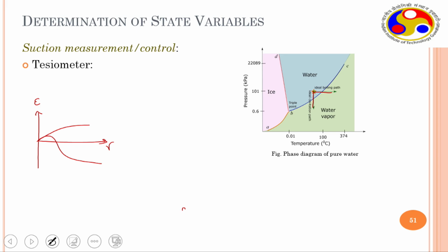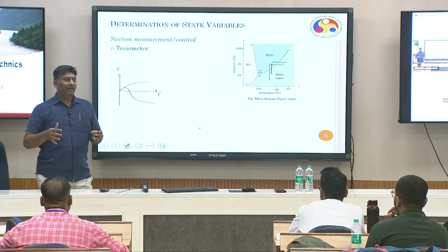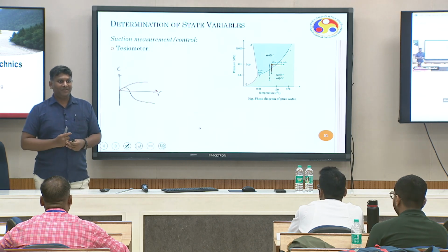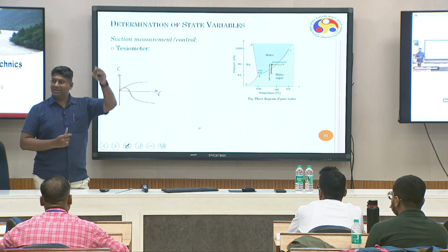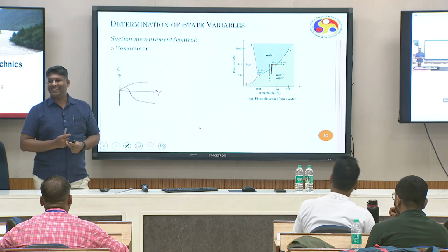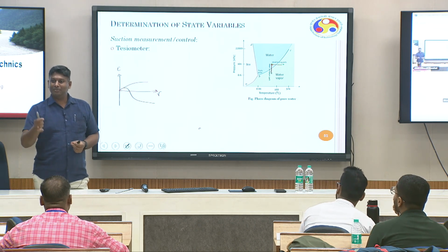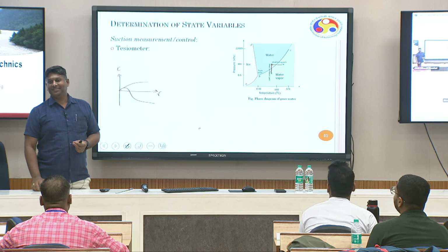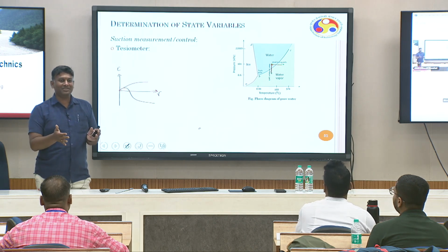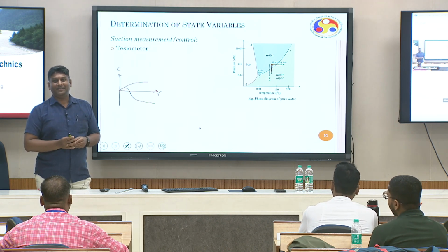100 kilopascal minus vapor pressure. Okay? So this is 100 kilopascal, or 101.325 in Guwahati. If you are measuring somewhere up in Arunachal Pradesh, what will happen? Atmospheric pressure itself drops to 80 or something. Your measuring range also drops. So then you can only measure a maximum value up to 75 or something. Beyond that you can't measure. Right?